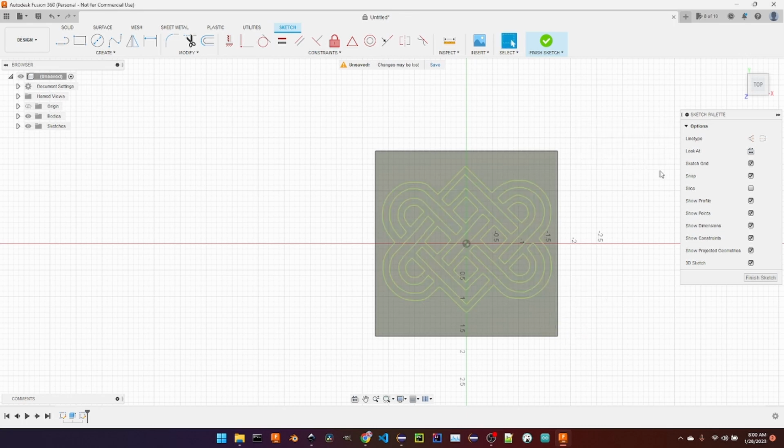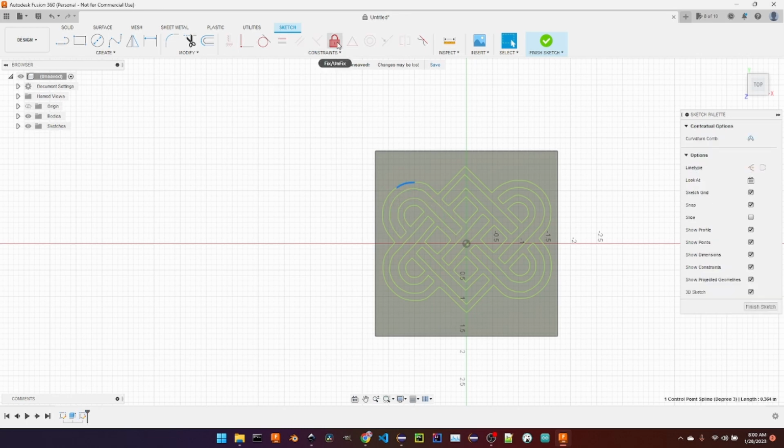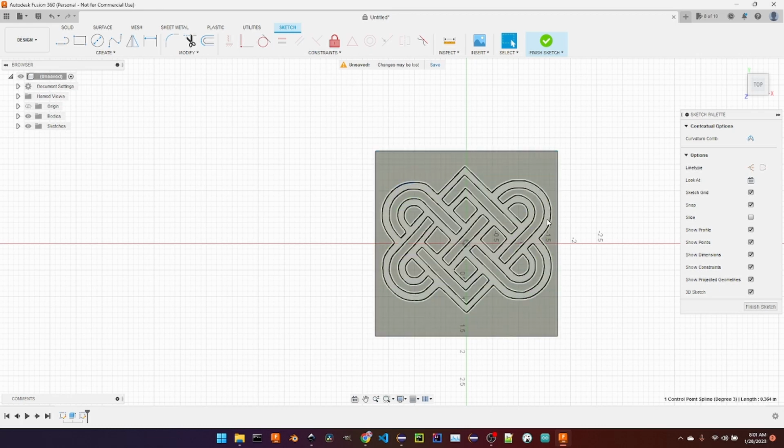I would say okay. Now this is looking green. What does the green mean? Green means it is all locked in. If you look at the constraint, if I select this, the lock is here. That means it's a locked constraint, and I cannot edit the points and I cannot mirror it. If you look at this image, this is mirrored, this is mirrored, this is mirrored to this. So there are many different things that are mirrored to each other. If you want to convert into manual and then do it, it becomes difficult.